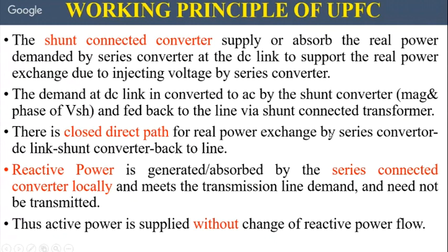So this does not necessitate reactive power to flow as per the requirement of active power. Up till now we used to see that without UPFC, if you want to control real power, it must be followed by reactive power, or without reactive power you cannot control real power.